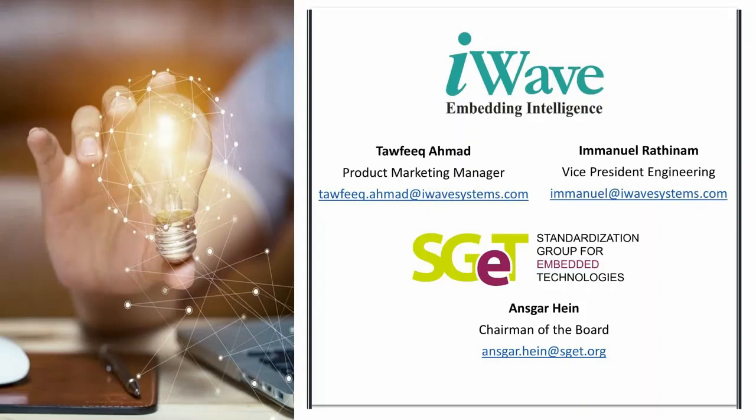So I will go to EMI and EMC effect. That's a very good question from Ravi Shankar. Definitely you need to take a lot of care during your layout design. You have to plan your layers, where the high speed comes and where the low speed comes, because the area available is very small. The traces are too tightly coupled, so you need to make proper spacing. If you take care in the design itself, then there is no problem in terms of EMI and EMC.